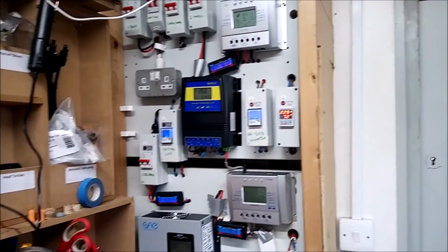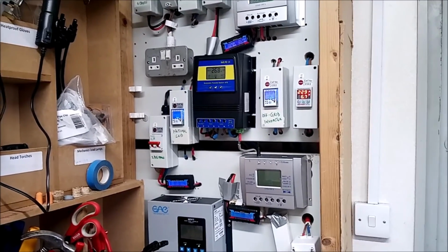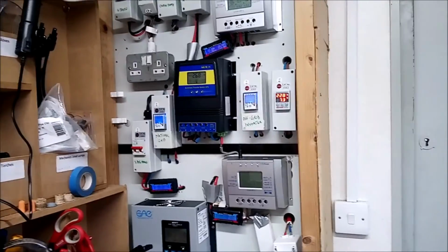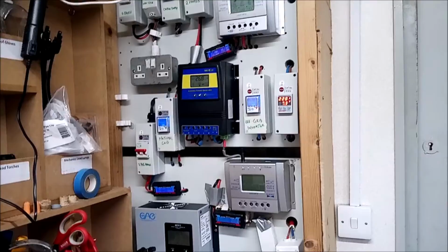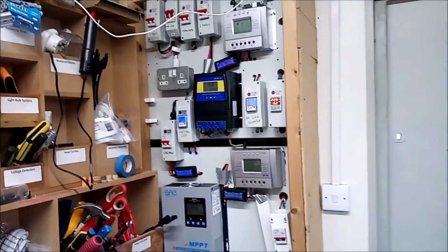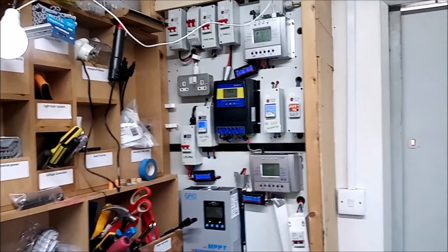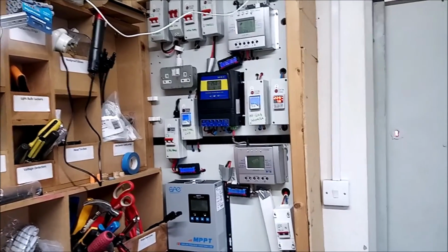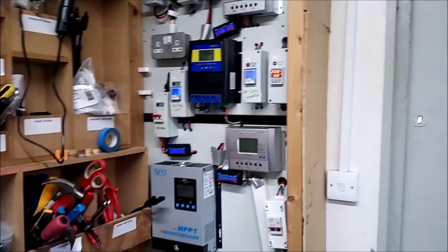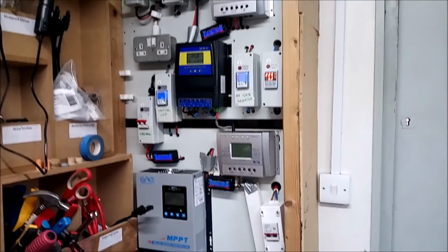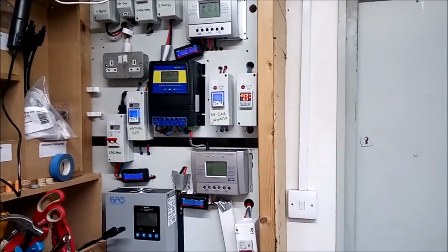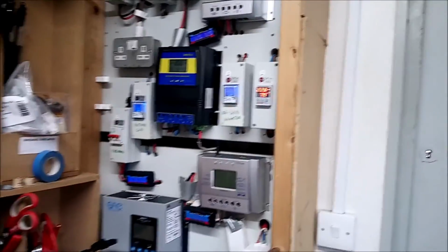You will need some space. I often prefer ground-mounted solar panels, but if you have enough space on your roof, please do go for it. Yeah, I'm using gel batteries. I've got 26 kilowatt hour gel batteries that I've combined together. Not all of them are from the same make. I have to because of the cost. I have to test them individually and then check their capacity just to make sure they would work together and one is not going to be draining down the power.